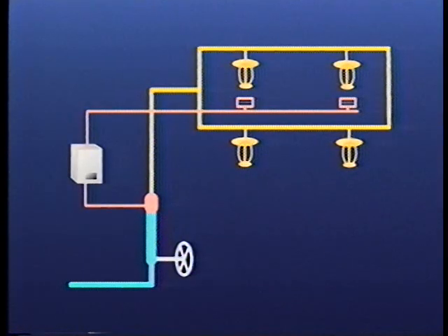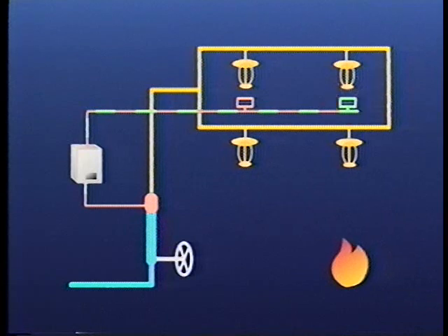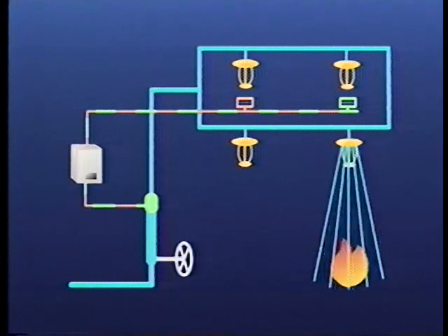A pre-action system uses a supplementary detection system containing heat detectors or smoke detectors. When activated, these detectors cause a valve to open, which in turn admits water into the system piping. In a pre-action system, closed sprinklers are installed on the system piping, which is then filled with a small amount of air pressure. The air pressure is provided only for supervisory purposes to detect leaks in the piping. At the time of a fire, the detection system activates to open the pre-action valve. This allows water to flow into the piping. Water will not be discharged from the piping until the sprinklers have actuated.